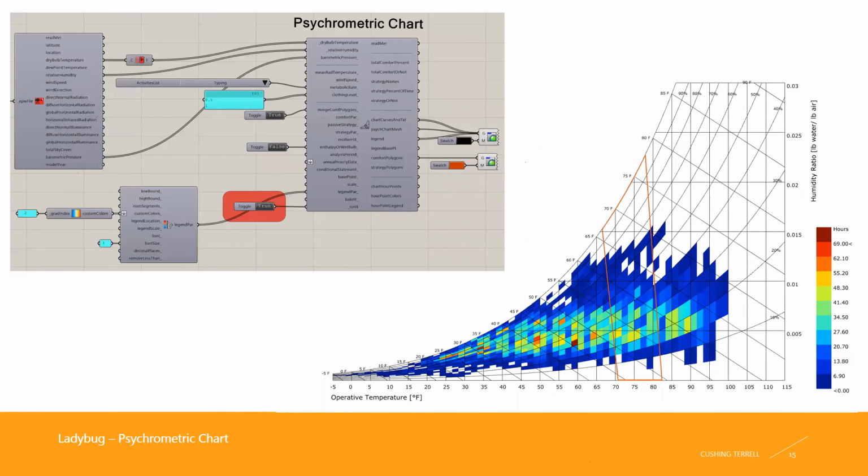It can produce psychrometric charts. You can take the dry bulb temperature from the EPW file and the relative humidity and the barometric pressure, and plug all this stuff in. There's a bunch of optional things you can change, such as the metabolic rate if you want to create a comfort polygon on the chart. In this case, the red outline overlaid on the chart is the comfort polygon for someone typing, and I've put in 2 clothing levels: 0.5, which I think is t-shirts and shorts, and then a clothing level of 1 would be like a 3-piece suit.